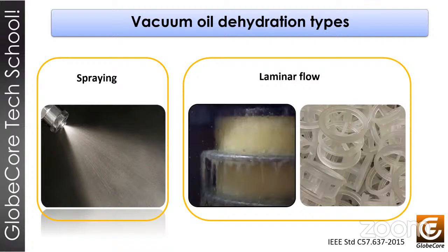Consider the consistent ratio of free and blocked passes regardless of direction. Large specific surface area, the volume ratio increases the surface renewal rate of the liquid film to improve mass transfer. The delay of two-phase contact facilitates highly effective contact and distribution. Relatively high liquid reserve contributes to high absorption efficiency, especially in cases where the reaction rate is slow. Uninterrupted and consistent passage of gas and liquid flow.